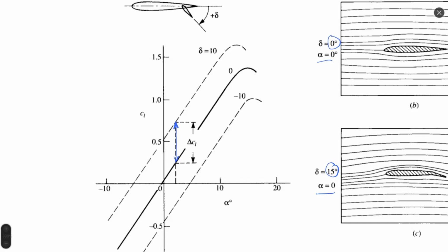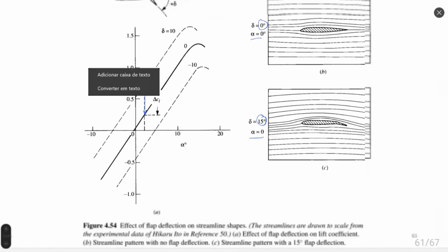So we have sustained high efficiency flight at high velocity. And then when descend, there are several ways, of course, controlled by motor, controlled by flap, but also having negative flap inclination, we decrease overall lift coefficient and we can descend this airplane.